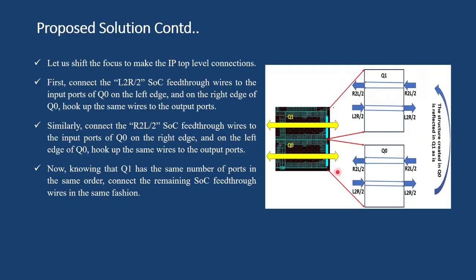So with this methodology, we are able to use the SoC feed-through lines crossing over these MIBs effectively. By doing so, instead of dealing with 6K nets in one partition, we will be implementing only one partition, which is just getting reused as the Q1 instance over here.